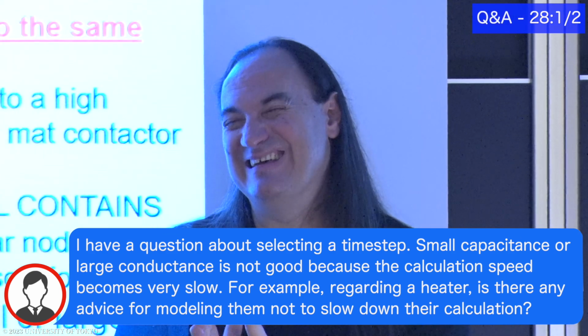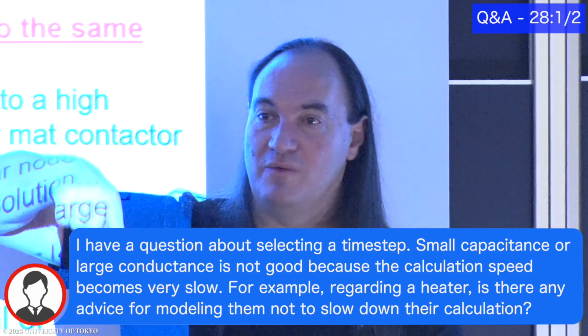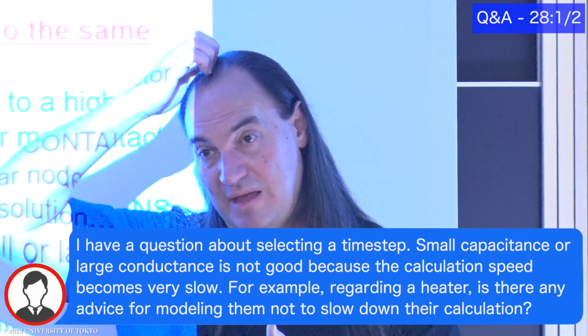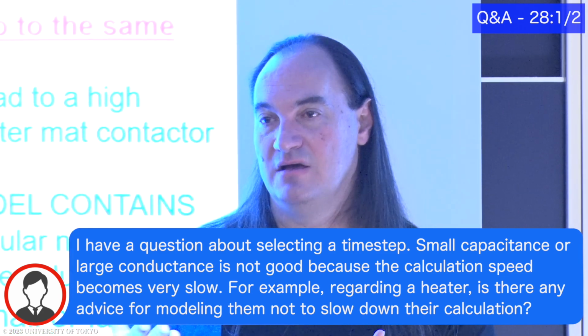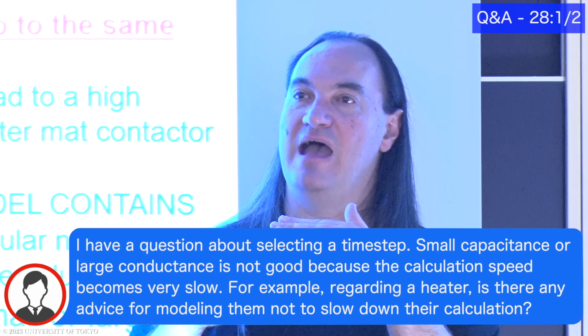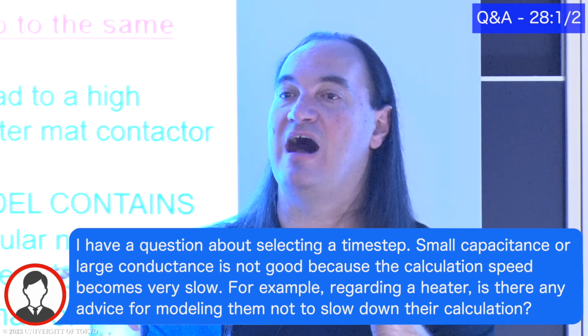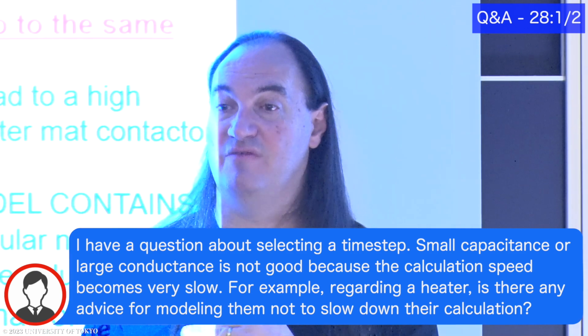But basically, the trick is you need to do something to prevent the heater from wanting to oscillate. Sometimes that can be widening the range such that you dampen the gain. Other times it can be finding ways to smooth out over time or over iterations the oscillatory behavior to a constant value.